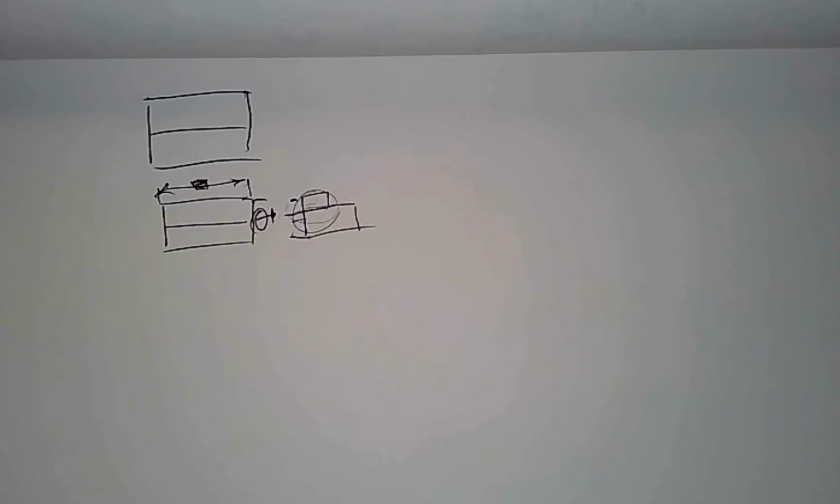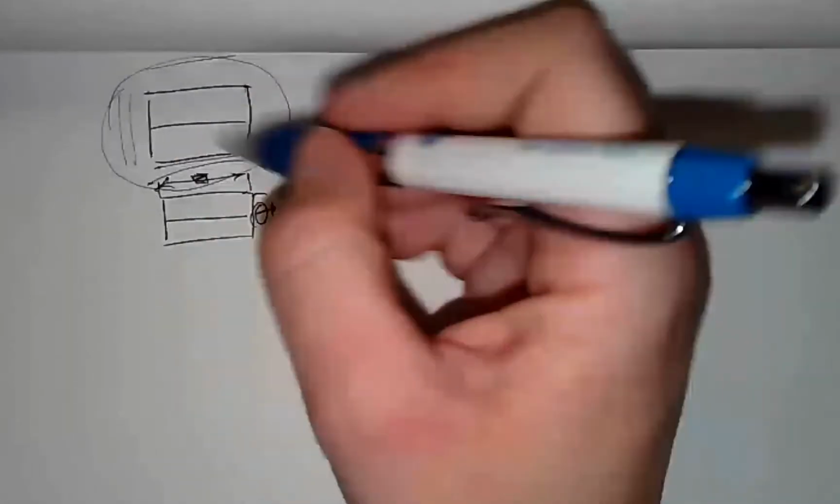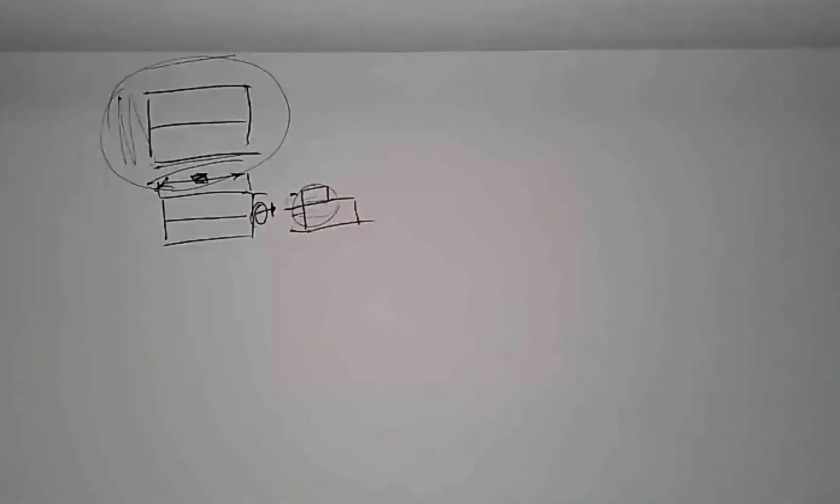So another thing that you want to do is avoid putting dimensions on all four sides of a view if you can. Keep it clean on the top and the side, or in the space in between and on the sides. That is going to make the drawing clearer for the person who's seeing it. There are also cases when you would be clearer by placing a set of dimensions on one side and another set of dimensions on the other side. So clarity is really your most important goal.